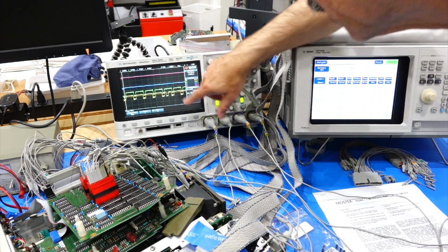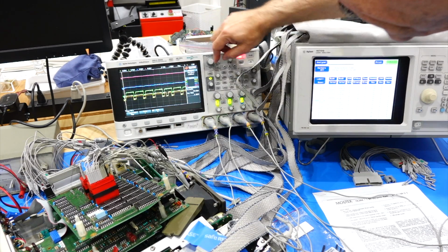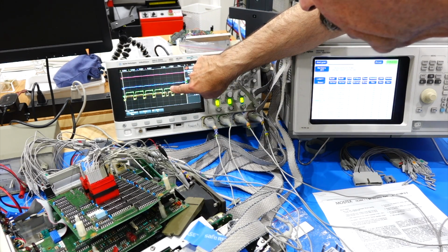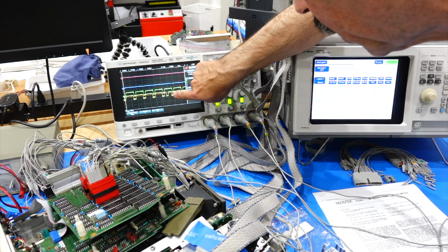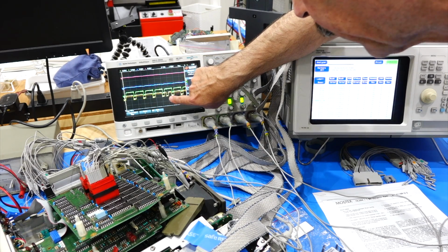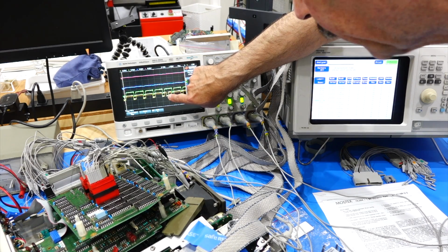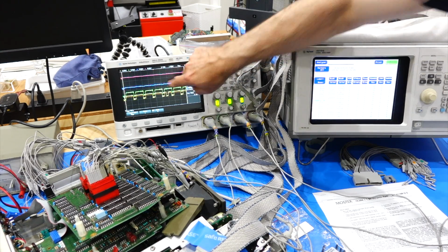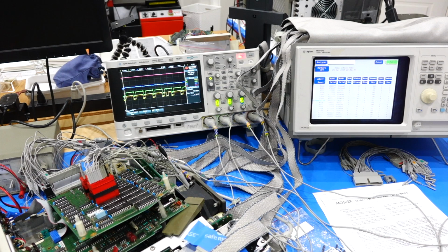Okay, yeah. So refresh cycle happens when there is a row selection not followed by a column selection. There should be a row column. But if it's just row, this is not for the purpose of reading. There is no column, that's a refresh. So the refresh circuitry is commanding a refresh, but it's only taking care of one address. So this is probably what's happening. We have only 1 byte of memory or 1 word of memory in the whole thing that works. It's never translating the addresses. Addresses don't come to my RAM chip.